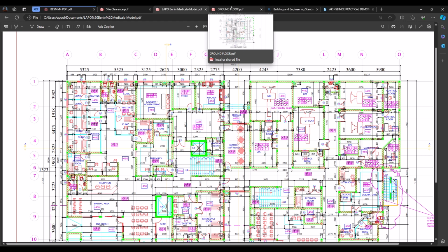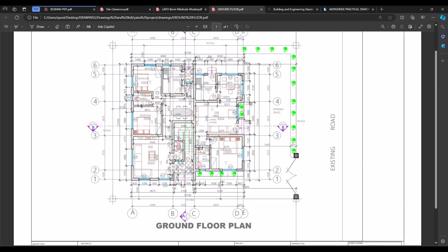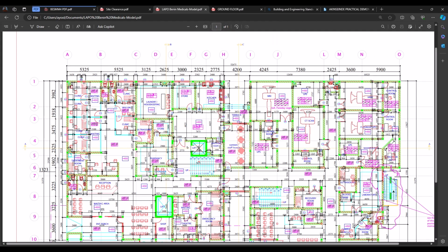In this situation, we might have two scenarios. One, a situation whereby the architect does not provide the site plan. What are we going to do? And also, we have a situation whereby we have the site plan. So for the case with no site plan, in order to do effective takeoff, we need to allow access for temporary site activities such as a mixing area, temporary site storage, temporary site meeting or site office, and the like. So we need to allow a spread around the perimeter of the building, or offset. The minimum we can allow is 600. You can do as much more as you want, but the minimum should be 600 in order to allow us space around the building and also use it for other activities.